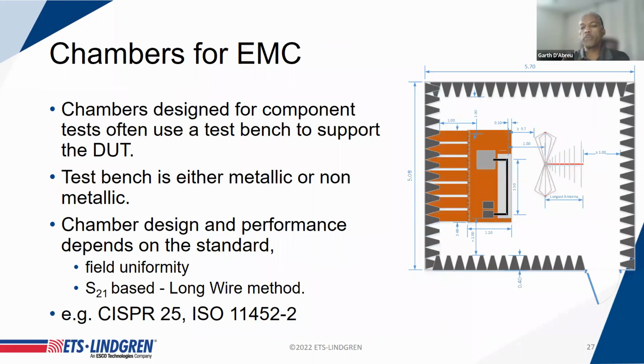And I touched on these chambers. These are the standard component level chambers that, again, we're all mainly familiar with for CISPR 25 and ISO 11452 type measurements. And as a coincidence, it's almost exactly the same facility that you'd use for DO-160A and MIL-STD-461 component testing. In fact, these chambers are sort of the grandchildren of the MIL-STD traditional component test setup. Not very much has changed over the decades in the design of these facilities.